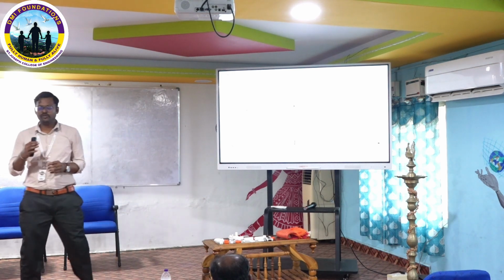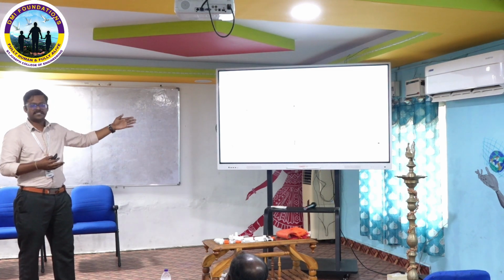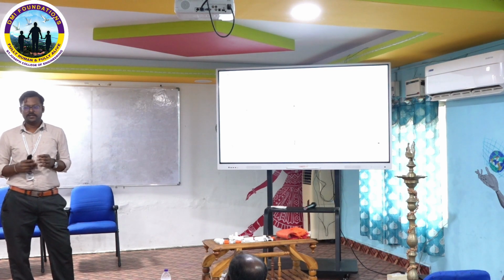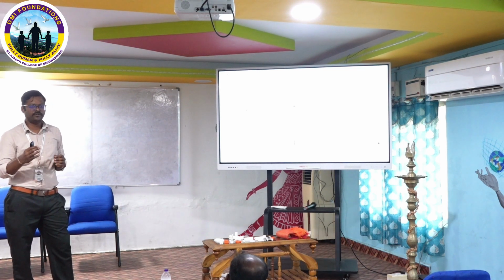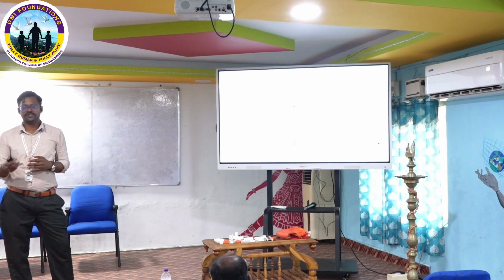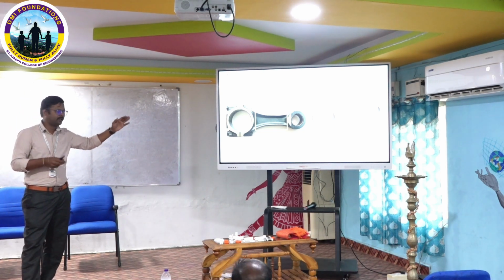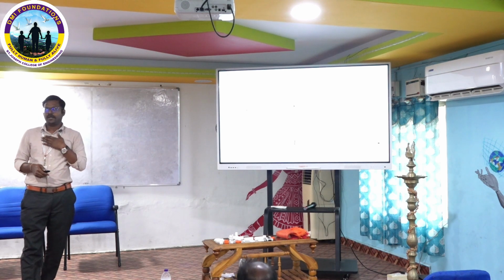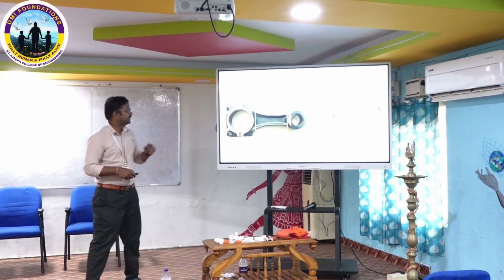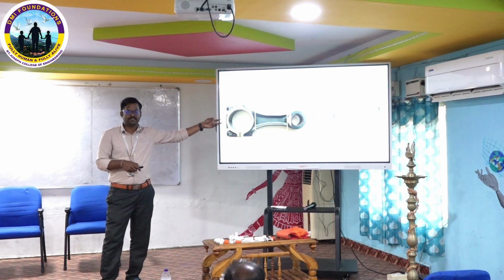So whenever you are going to do research or new product development using a lattice structure, you have to finalize which structure you are going to use. Then based on that you select your unit cell, and incorporate that unit cell into your structure. Once the previous step is completed and I have selected my unit cell, what am I going to do? I am going to finalize where I am going to incorporate my lattice structure. That is called the design space.